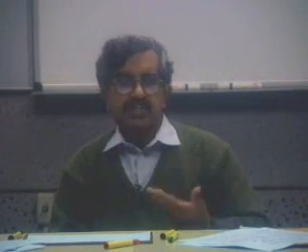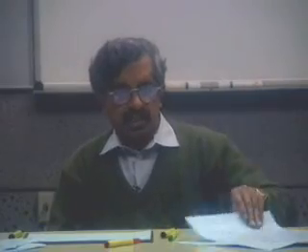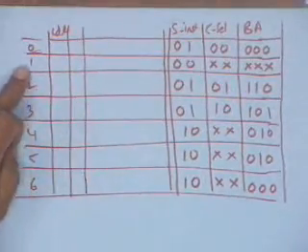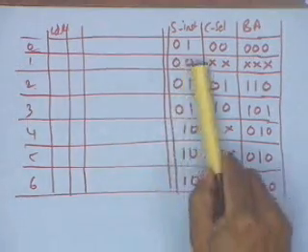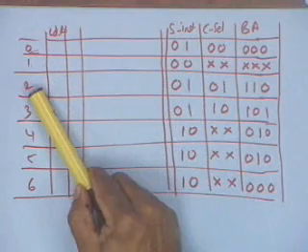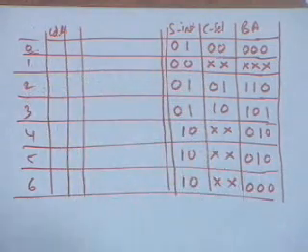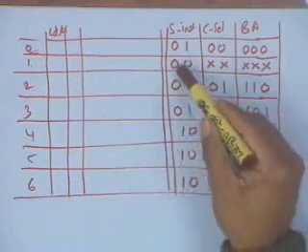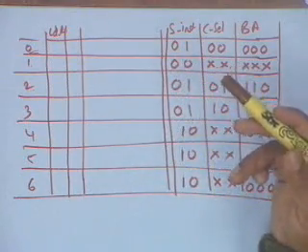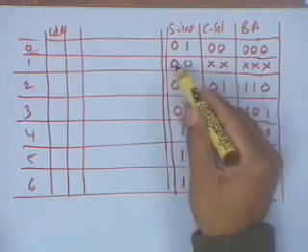Next means we go to the next microinstruction. When I say next or continue, that means if I am executing microinstruction 1 and I have a next sequencer instruction, I will go to 2. I can replace it. You can actually replace this next by an unconditional branch. You can, instead of doing this,